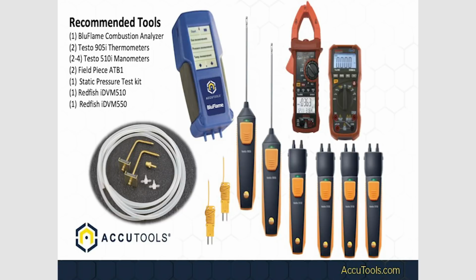How many of you guys have constantly measured your incoming gas pressure and noticed times when the gas pressure dropped too low for the regulator to regulate, and now we've got a flame that is not working correctly? Somebody turns on gas logs, somebody turns on the dryer, somebody turns on something else. If you're not watching incoming gas pressure at the same time you're watching your manifold pressure, you're missing a problem that could potentially be happening. If you're not watching your temperature split at the same time, you're missing things. If you're not watching your combustion, you're missing things that could be happening.